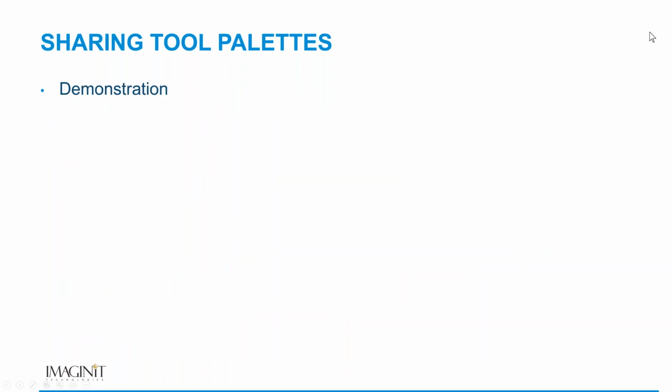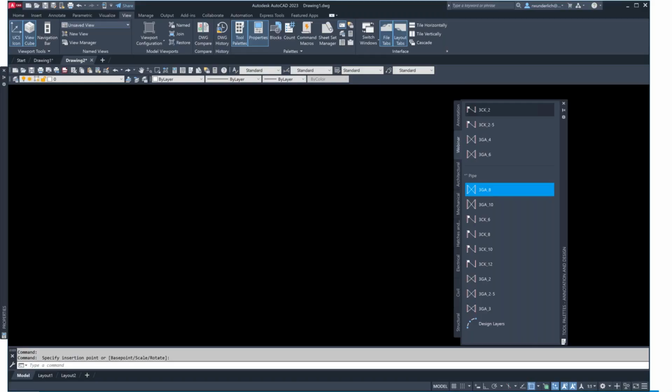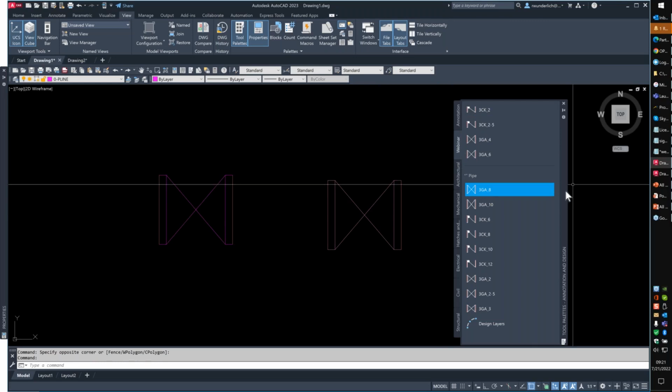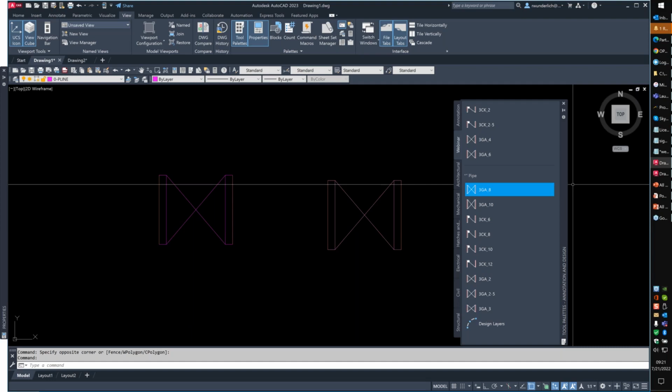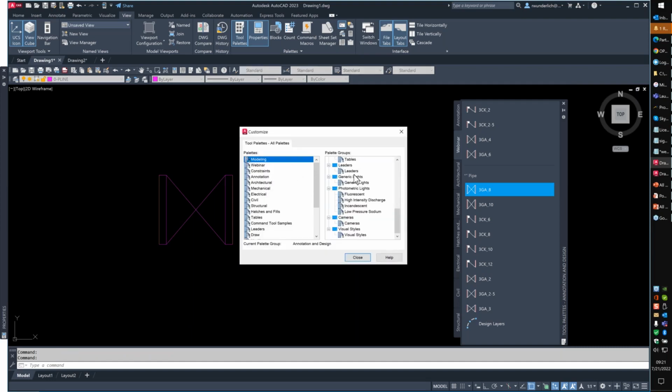So let's get back to sharing. Get back to my AutoCAD. Where did I hide that? All right, so now we have this new webinar one. I'm going to right mouse click and go to Customize Palettes. Oh, I forgot, what I didn't show you is that we're going to create a new group. I'm going to drag this group up to here. That's a new group, and then I'm going to grab my webinar right here. So there's my new group.